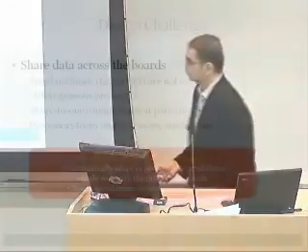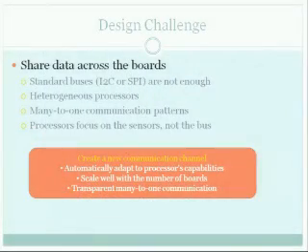And the way most people do that right now in the current state-of-the-art platforms is by using standard buses like I2C or SPI. Now, the problem of these buses is that they are extremely inefficient. For instance, you can imagine having two ARM processors operating at 60 megahertz and exchanging data over a serial I2C bus that operates at 400 kilohertz. It doesn't make any sense. In addition to that, if you have multiple processors, many of them might want to communicate at the same time. You don't want a communicating pair of processors to block any other communications that might want to take place at the same time. To deal with these problems, we've actually created a communication channel.